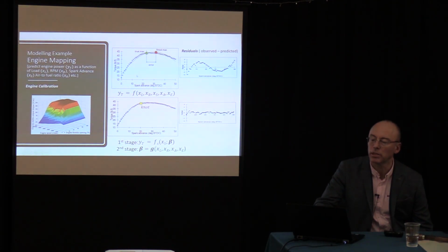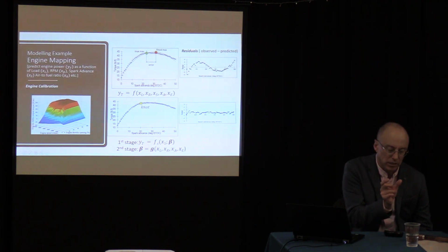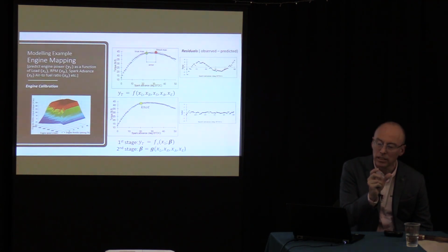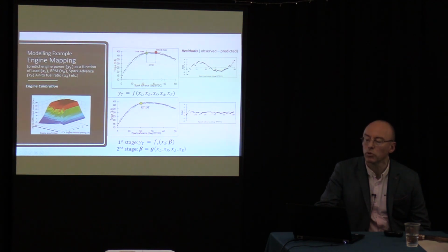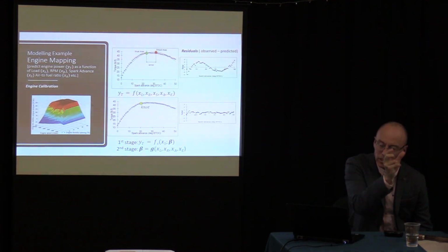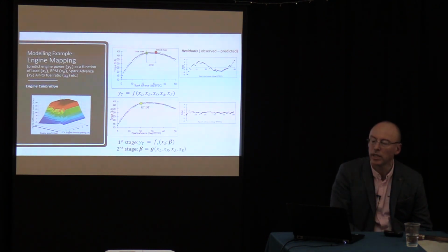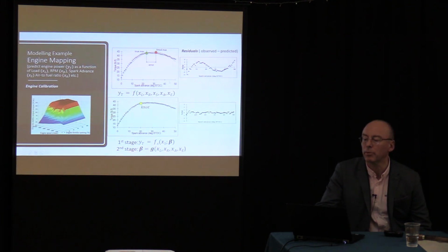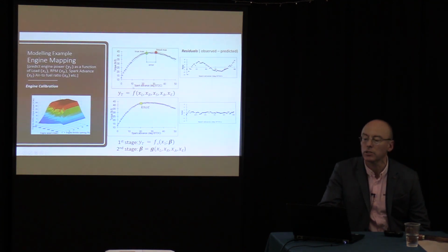This problem came to me early in my Ford career. So engineers were collecting data. On that engine study, I mentioned you can actually change where the spark plug ignites the mixture. That's called spark advance, and these are degrees before top dead center. So when the piston comes up to its top dead center, you can choose either side of that point where to ignite the mixture. And typically we ignite the fuel before it gets to top dead center. So these are spark advance degrees before top dead center.